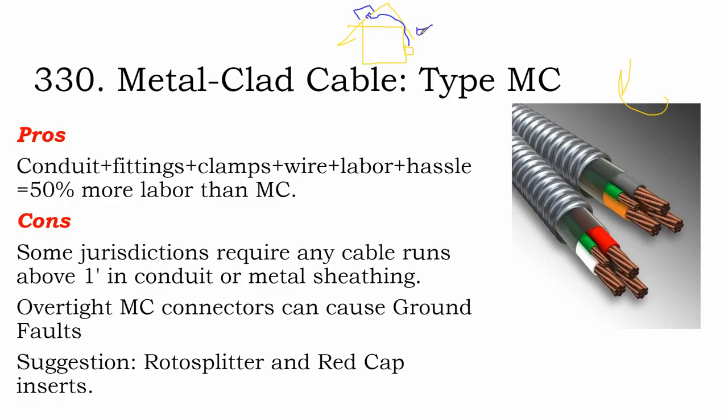At this point, you have to end your MC cable right underneath the soffit so that it's still protected by the weather. If you run your MC cable all the way down to the inverter, the inspector might say, well, that's not rated for that. So what you can do is buy the length of MC cable to go down to the inverter and then just peel off the metal wrapping and then transition that into EMT conduit.